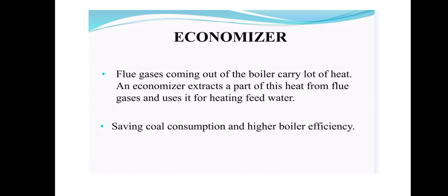Economizer. Flue gases coming out of the boiler carry a lot of heat, and the economizer extracts a part of this heat from the flue gases and uses it for heating feed water, saving coal consumption and giving higher boiler efficiency.